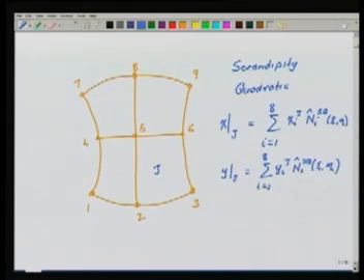In doing this, what do we have to do? We'll have to put additional nodes in the element. So we'll put these nodes somewhere in the middle of the edges. You can put it anywhere, but if you put it too close to one of the existing nodes, then the mapping has a problem. So let's decide that we'll put it somewhere close to the middle of the edge. Middle of this edge, middle of this edge, similarly here. We'll do it for all the elements, and create these nodes in the middle of the respective edges.